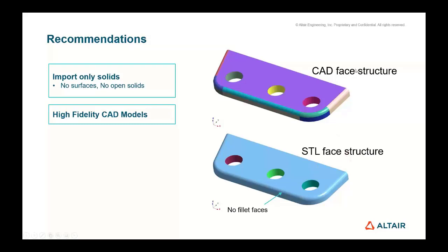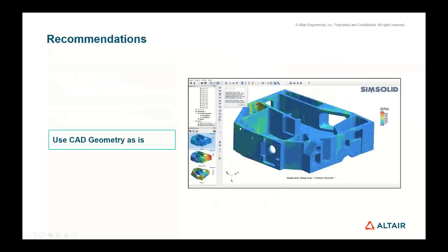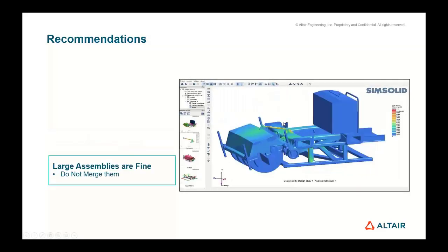And just so you know, you can work with CAD as well as STL, so any scan data that you have, but just be careful because with scan data, it will assume all of it as one surface. So if you can bring CAD in, just bring your CAD in. Use your CAD geometry as is. So where you have pinholes and everything, don't feel like you have to remove them.